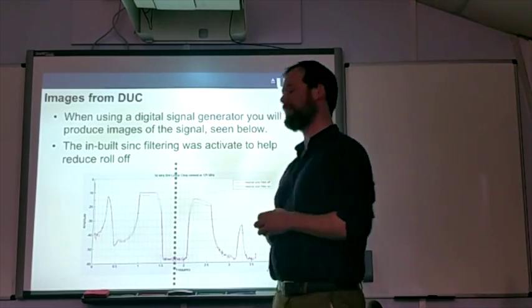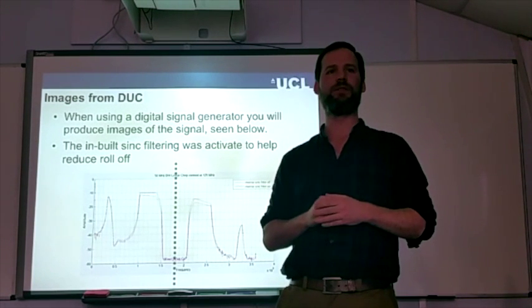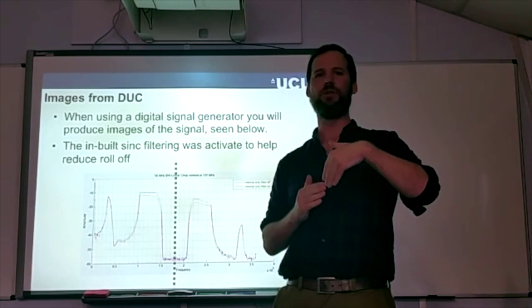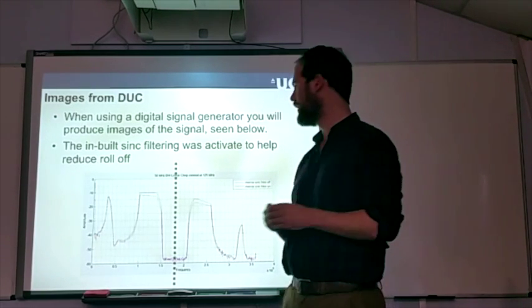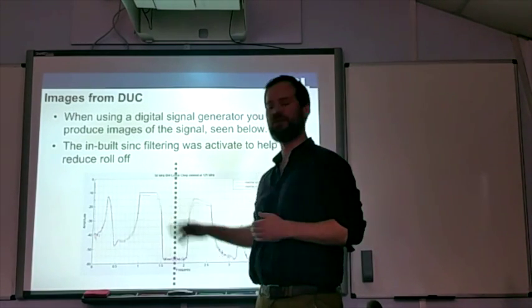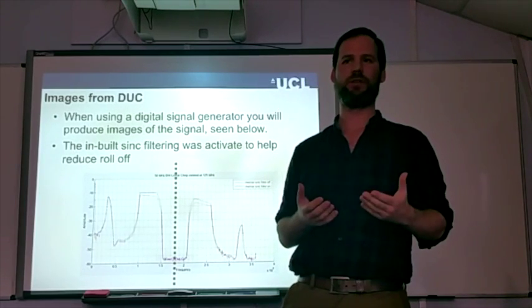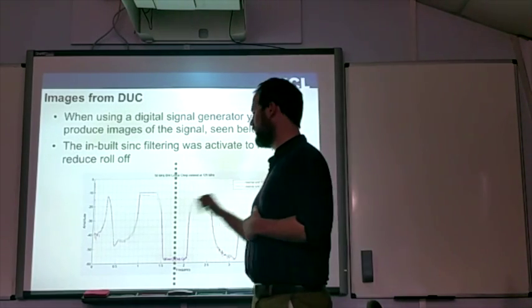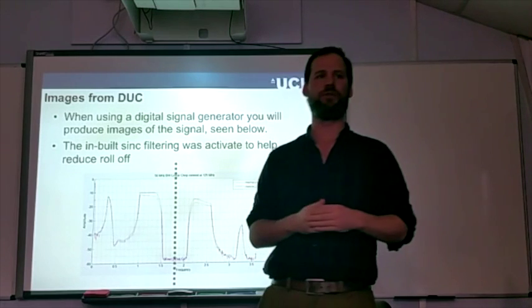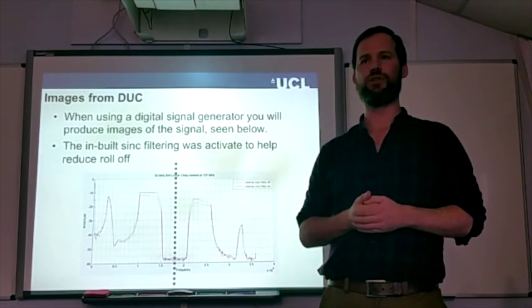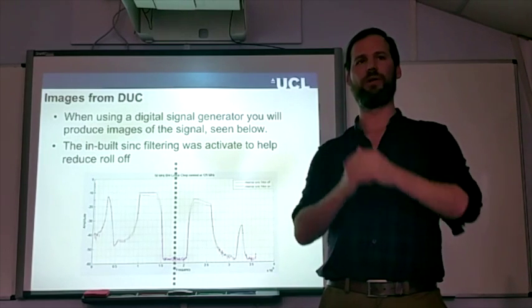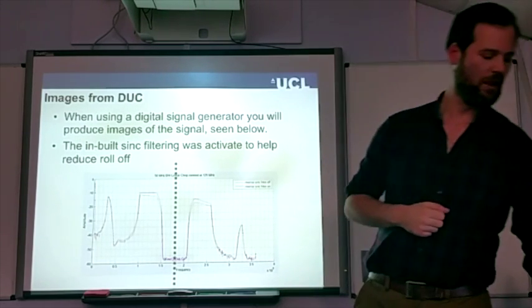Also, the Pentek has inbuilt capability of inverse sinc weightings, which can increase the amplitude at the higher end of the frequencies. You see this red curve has those weightings not turned on. When you turn them on, that compensates for the loss or roll-off within the band to try and reduce some of that spectral roll-off that we were seeing.